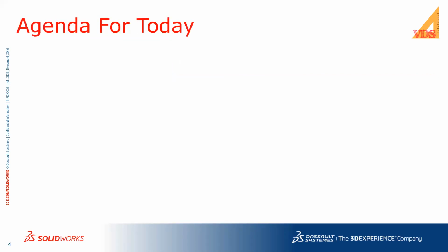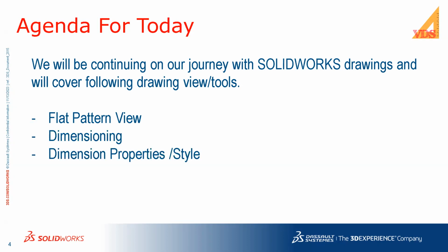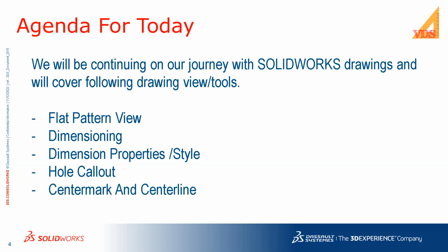I'll quickly go through the agenda for today. We have been working with SOLIDWORKS drawings since our last two sessions. So we will be continuing our journey with the SOLIDWORKS drawing, and we will be covering the following tools and views: flat pattern view, dimensioning properties and style, hole callout, and then Centermark and Centerline. So let's not stretch this further and straight away jump onto the presentation.